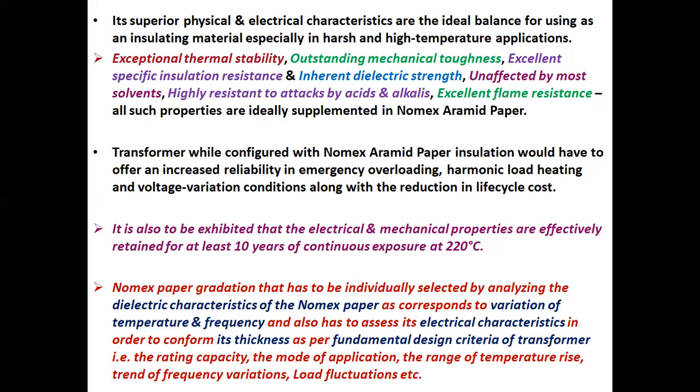Transformer, while configured with Nomex aramid paper insulation, would offer an increased reliability in emergency overloading, harmonic load heating, and voltage variation conditions, along with the reduction in life cycle cost. It is also exhibited that the electrical and mechanical properties are effectively retained for at least 10 years of continuous exposures at 220 degrees centigrade.